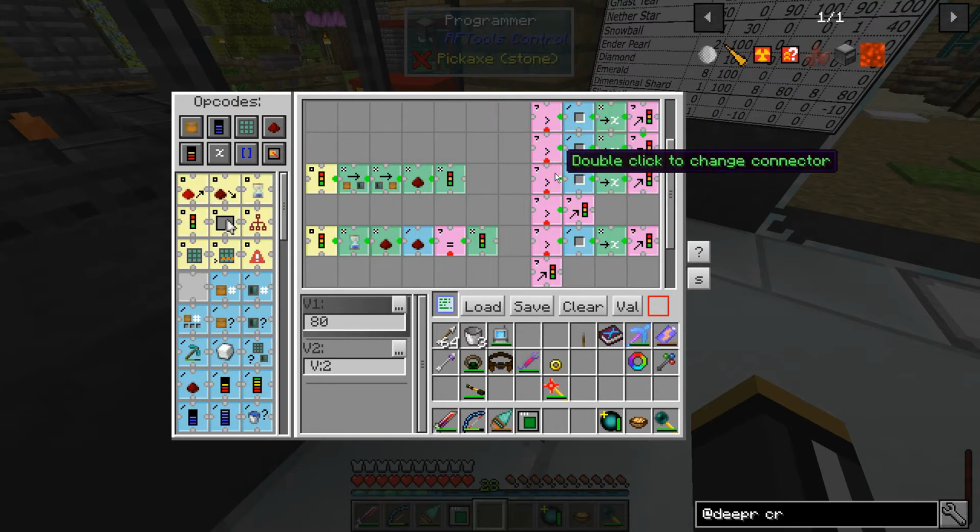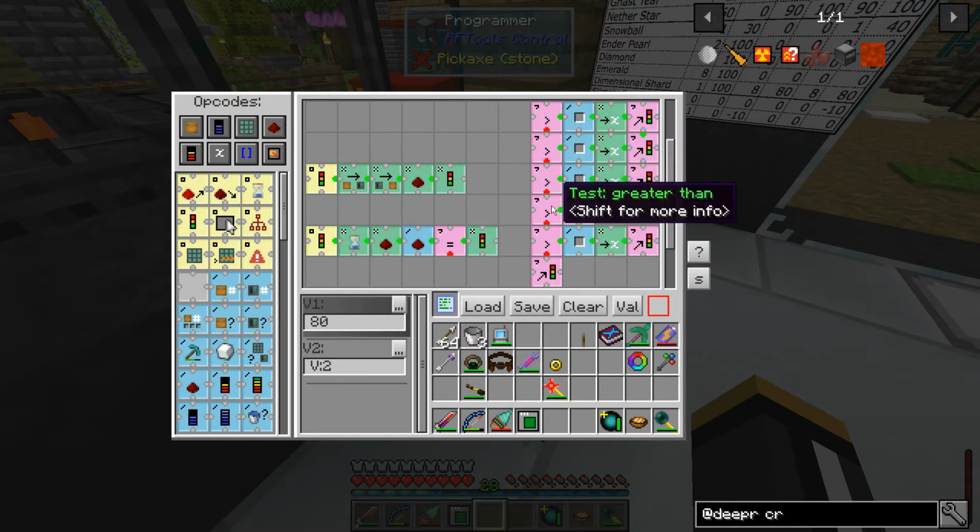But now, at this point, our purity is probably really low because we've been pumping in all this stuff that takes our purity down. So now we're just going to wait. We're going to call the function wait if our purity is less than 85. So we're saying, is 85 greater than our purity, which is in variable number 0? Then we're going to call the function wait. We're going to wait 3 seconds, and we're going to check every 3 seconds. Is it up to 85 yet? If not, we're going to wait.